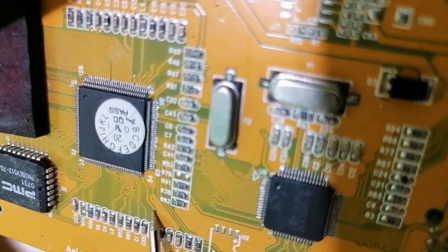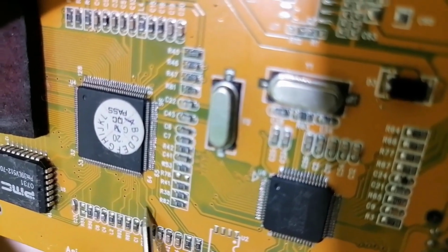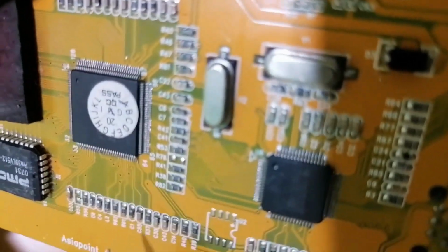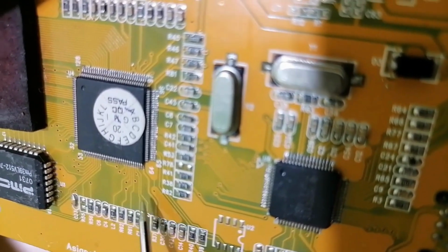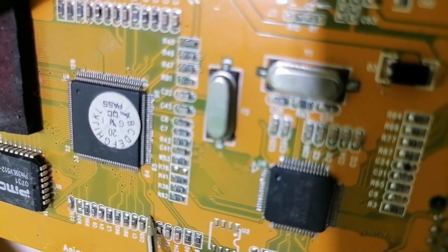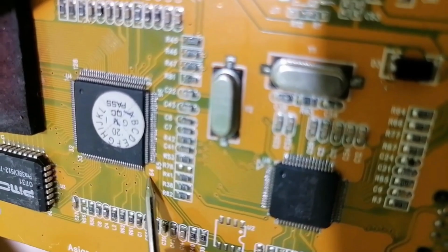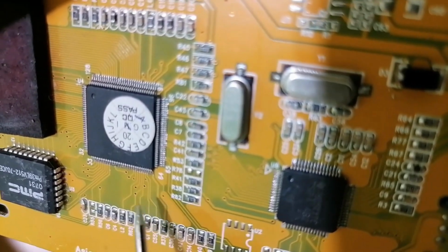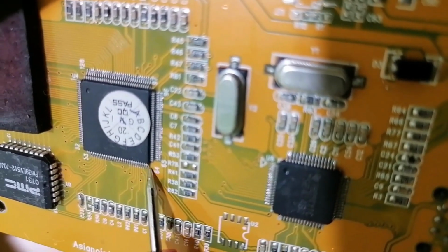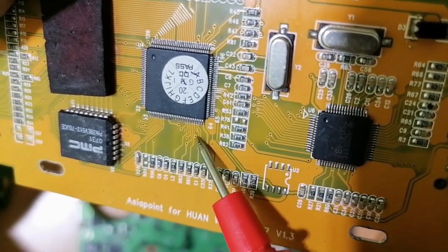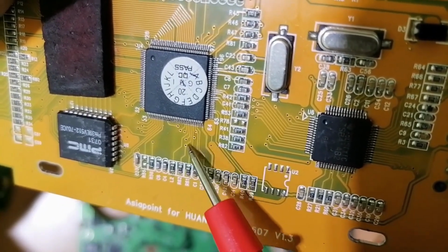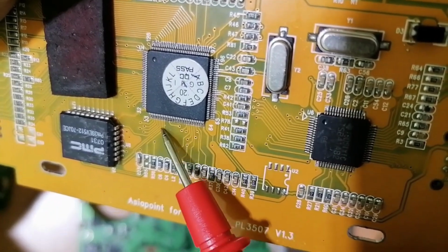So I want to share with you here a very important tip. If you focus here, as you can see, we have these paths, these lines. Do you see? These lines are not the same as this one. So this is a bolded line. This bolded line means here we have power, here we have VCC. And those thin lines, as you can see here, are just control signals.